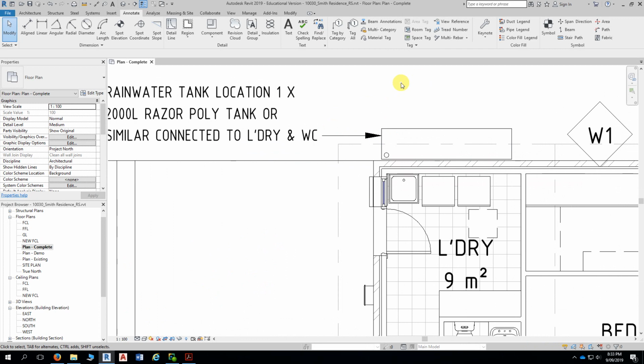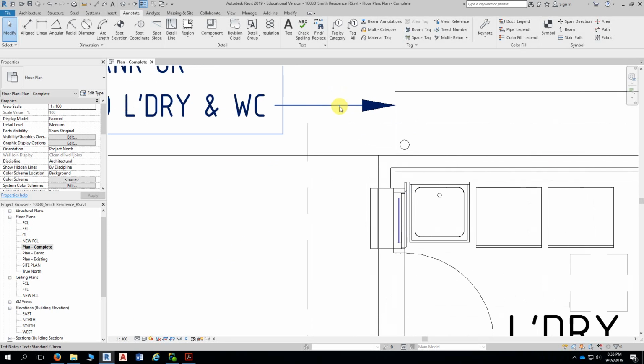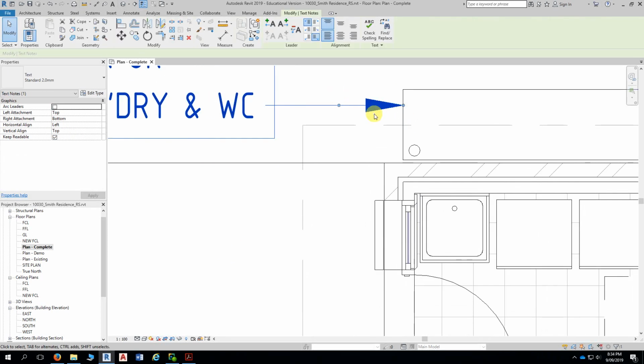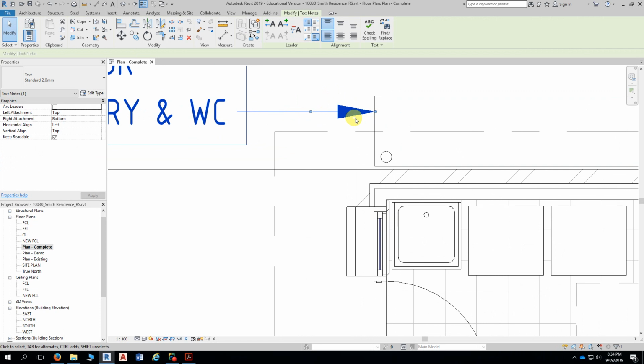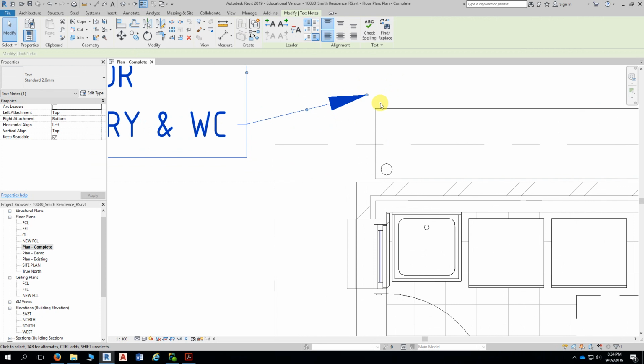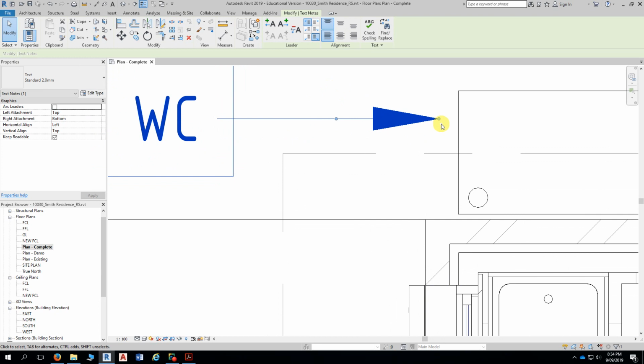How will we ensure that the arrow line is straight, because mine is not coming straight? The arrow itself is comprised of two dots, this one and this one. So if you drag that one up, it's obviously not straight. If you bring it down, it will lock into level at a certain point. Even if you have to get in not really close, see that's not level. See the stepping? At a certain point it will actually lock into level.